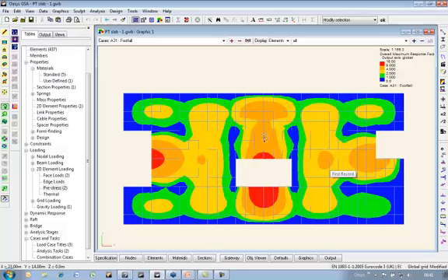There are areas of the floor which are okay for standard office, and some bays around these openings which the occupants would find quite lively unless they were restricted to sort of service or reception type areas or so on. Now this is looking at vibration over a whole slab.